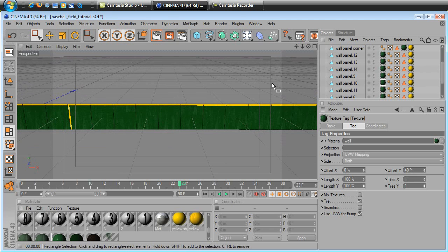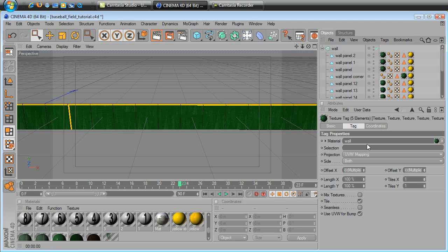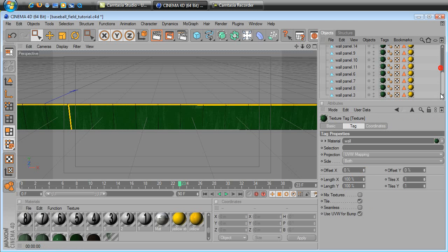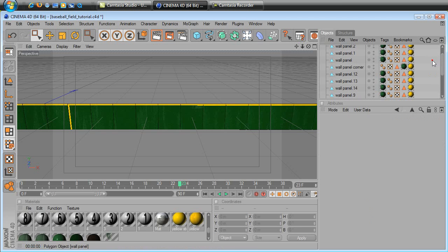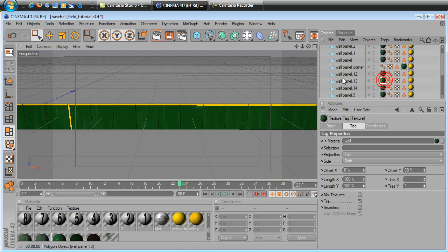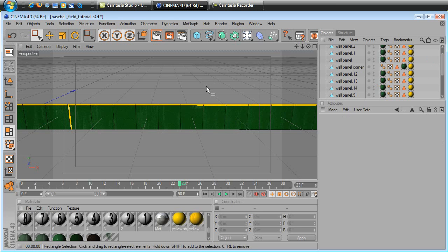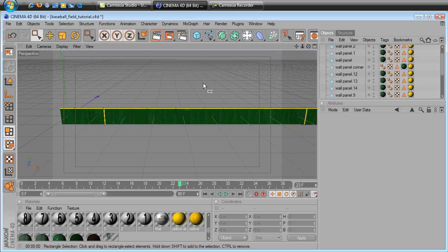Okay? And you'll probably get the best results by changing the texture map projection to flat instead of UVW. I should have disclosed that. Change it on all of them to flat, except for the corner. I meant to tell you that. That way you can offset it. It's projecting the entire material as a flat map, and you'll get better results laying the grunge map over.